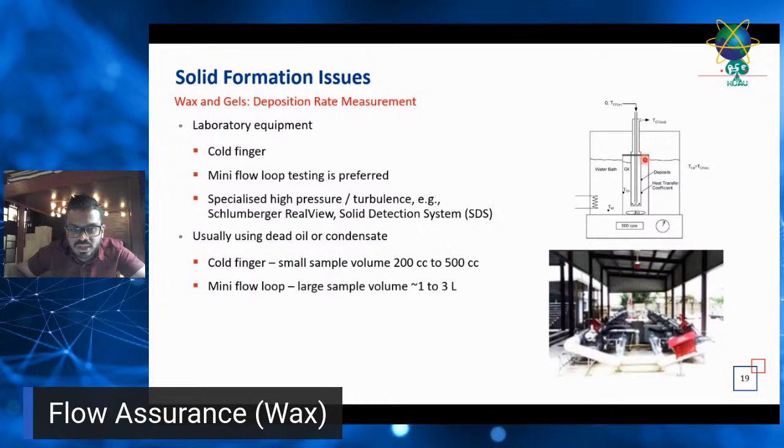So once we conduct this experiment, we need to obtain the amount of wax being deposited on this cold finger, or the wax mass flux, for a certain duration. We need that data later on to tune the diffusion coefficient, which I've shown earlier.